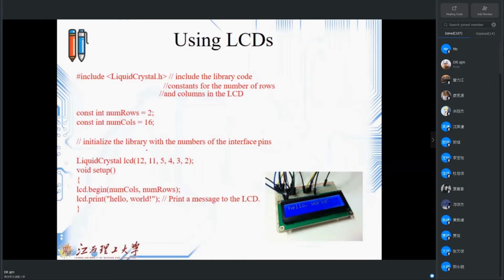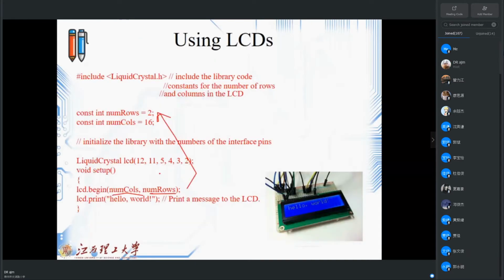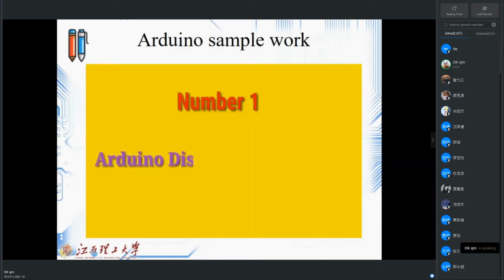Can we make it a little bit more technical? Yes. With LCD begin, you can write the number of columns and number of rows and specify that like this. There is no difference whether you put 16 by 2 here or put them separately, meaning you put some integer numbers and declare them before. There is no difference between this program and the previous one, but they call it the technical method of writing that. Okay, that is what we need to learn to work with the LCD part.